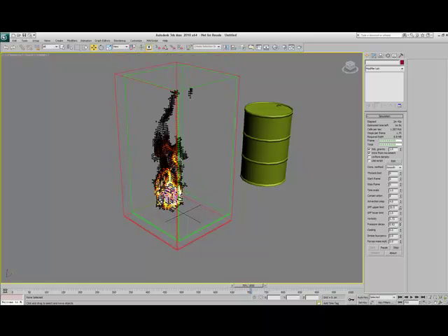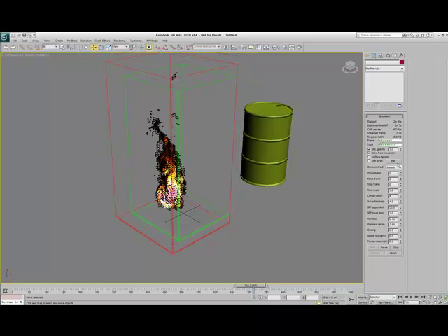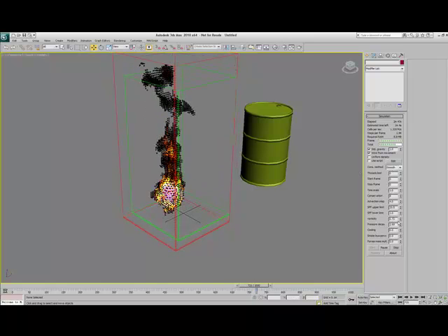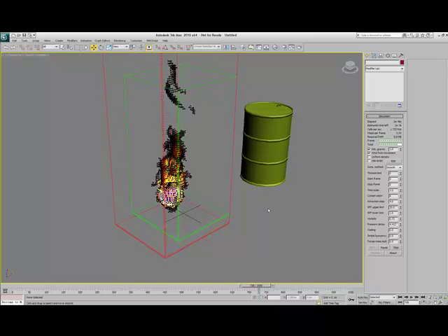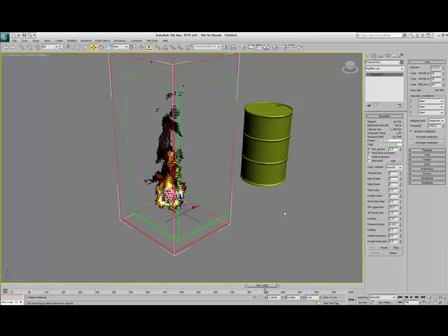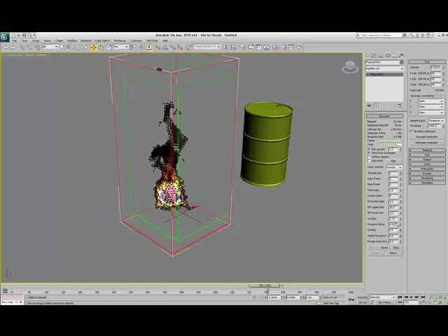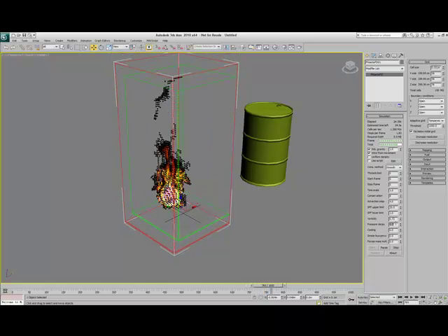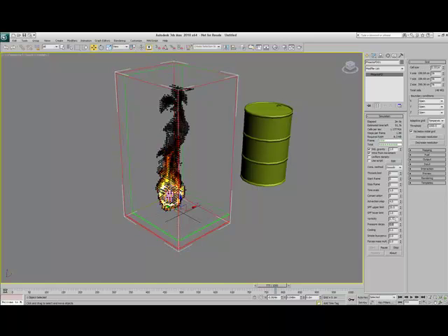The pressure decay parameter allows me to simulate the effect of atmospheric pressure dropping down as you get higher in the atmosphere. It is basically a multiplier, and it is useful if I want to simulate a very large explosion, like a nuclear explosion for example, which leaves a mushroom-shaped cloud.